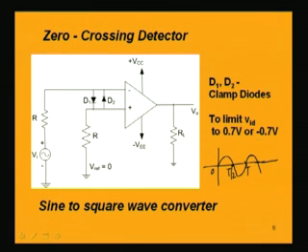So, a circuit which is able to detect the moment when it crosses 0 and in what direction. That means we are trying to detect at what moment the input voltage, which is a sinusoidal voltage, is crossing the 0 line and in what direction, that is, from positive to negative or from negative to positive, and that can be detected by the circuit shown here.